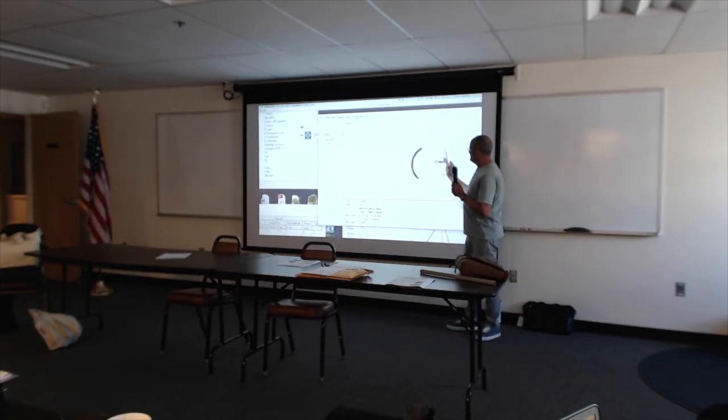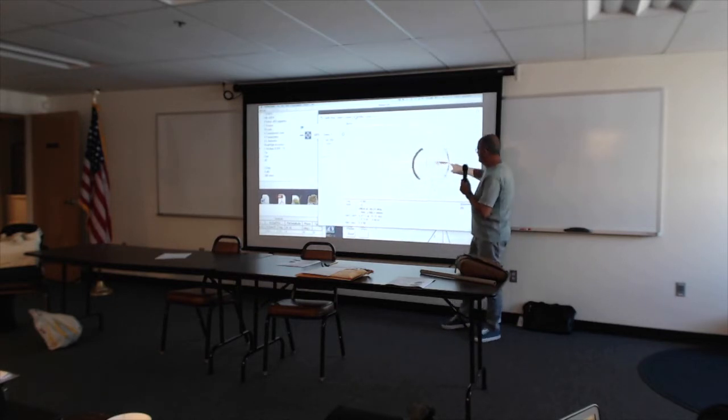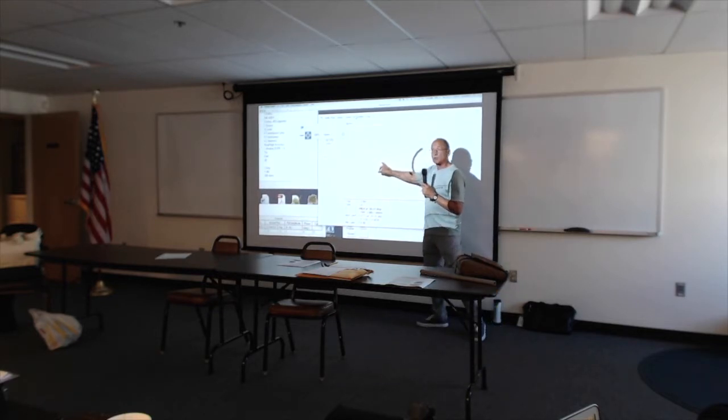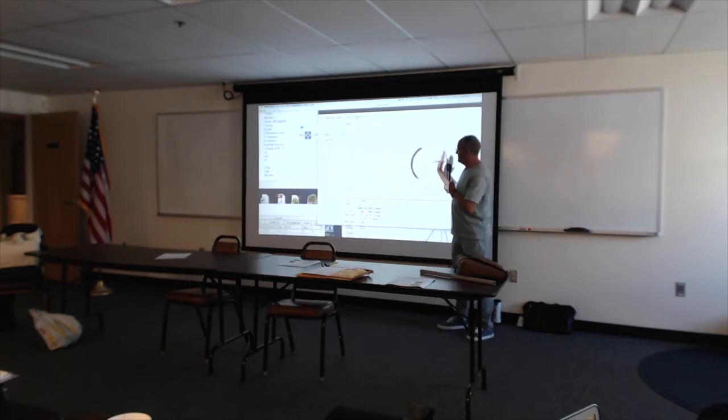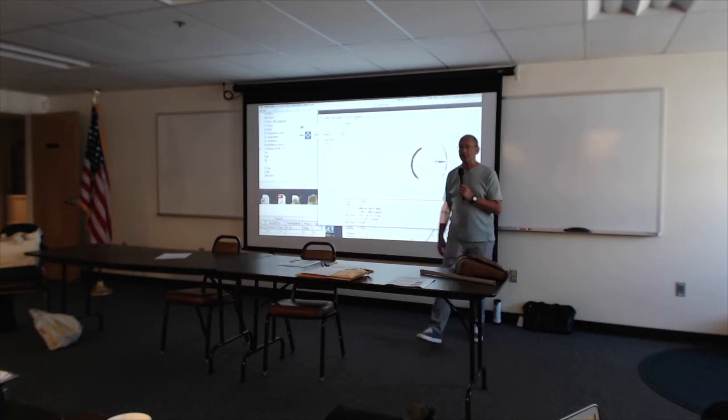So what I understand is there's a horizontal line going through this circle. At this point, this is as if the circuit is open, and at this end, it's a short circuit. One is usually the sweet spot here for the impedance. This is a relative number, and when it plots out the impedances, it tries to plot them along these concentric circles, to tell you how good or how bad the impedance matching is.